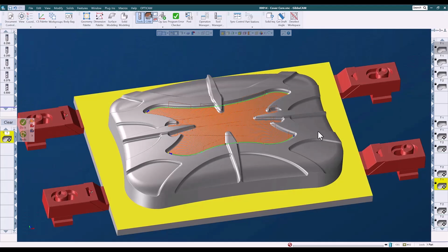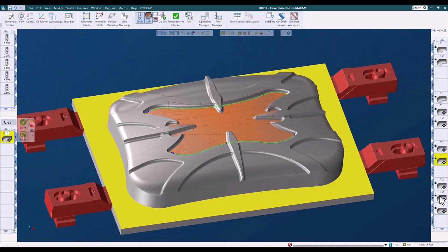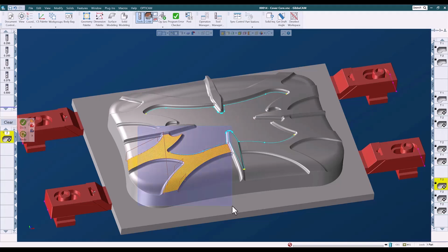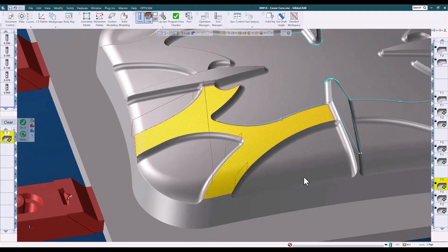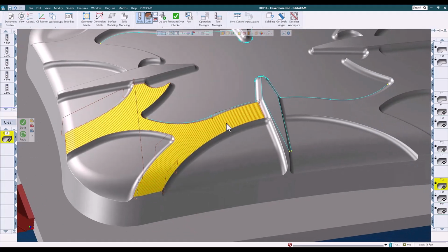Moving on to some of the other features, this is an advanced 3D spiral lace cut. By defining the center of this arc as the center of the spiral, limiting the tool to the silhouette of the surfaces, and running the tool back and forth, we get a really nice toolpath that somewhat flows with the shape and has minimal retracts.